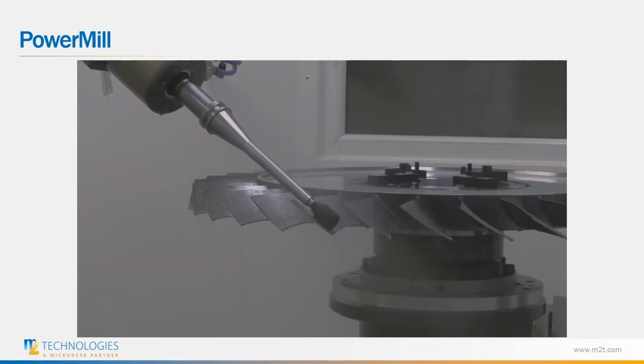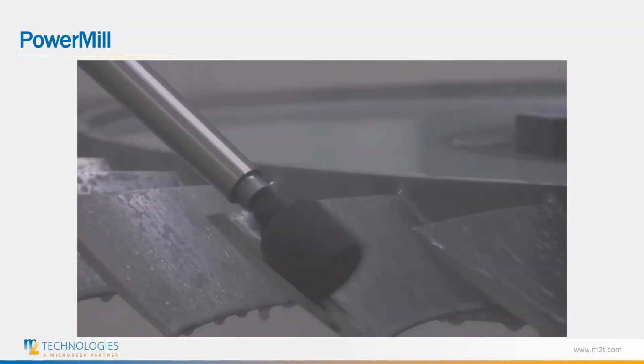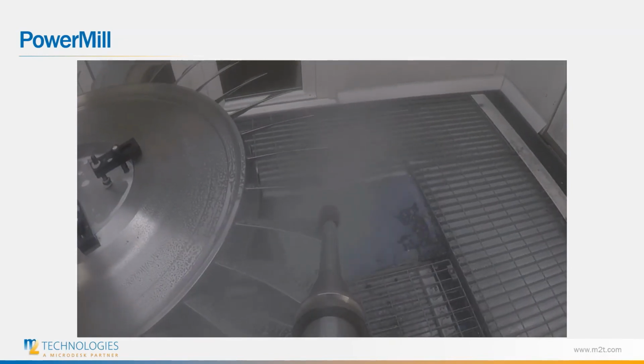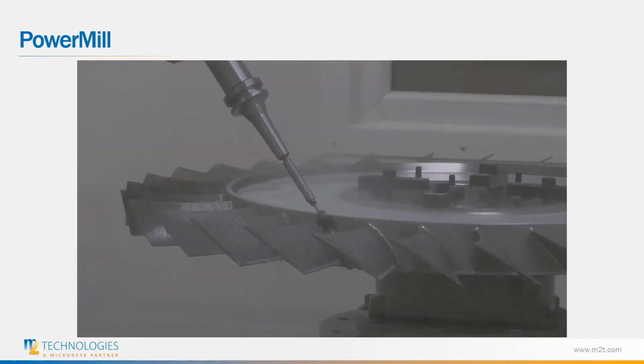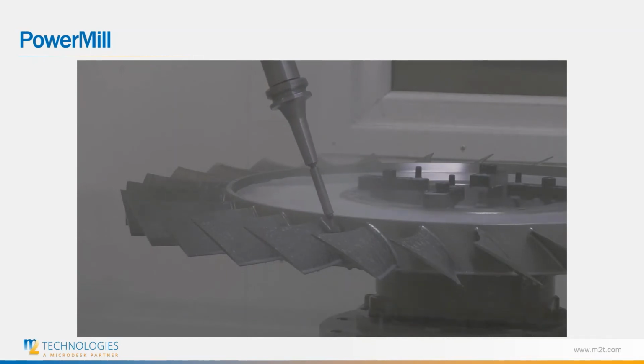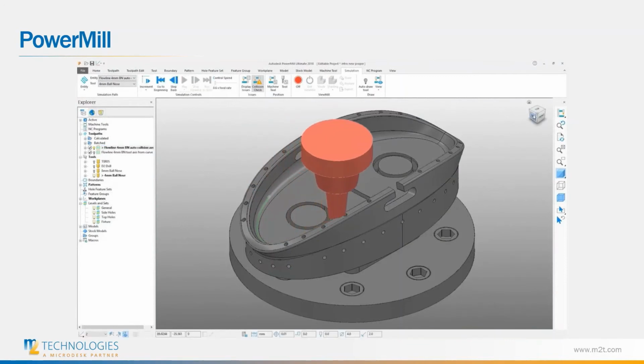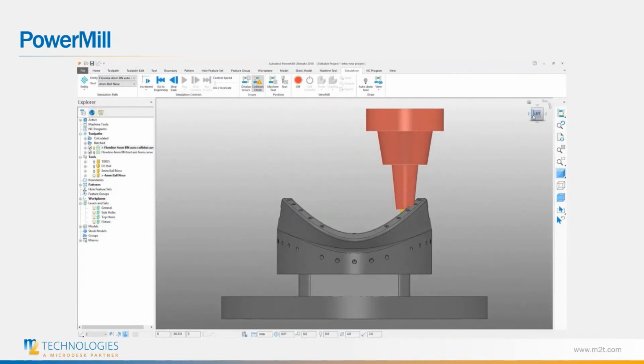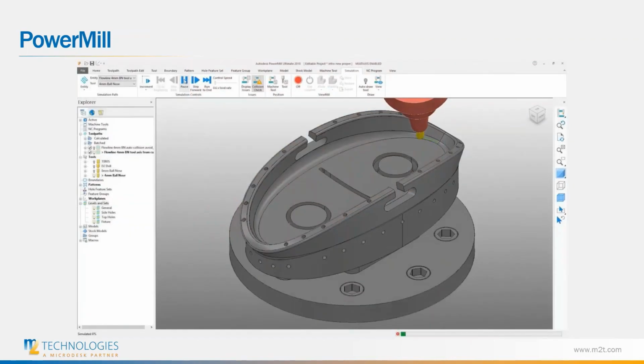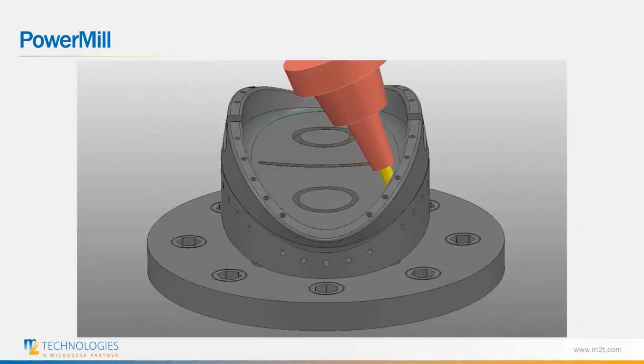Autodesk PowerMill provides tools to make efficient 5-axis programming a reality. Its comprehensive suite of toolpaths has been designed to help ensure parts can be manufactured no matter how complex. Instead of offering a small selection of specialized strategies, PowerMill allows 5-axis motion to be applied to the vast majority of its toolpaths. Strategies such as raster finishing, projection finishing, corner picking, and flow line machining can all be set to run in 5-axis mode by simply selecting the appropriate tool axis setting.